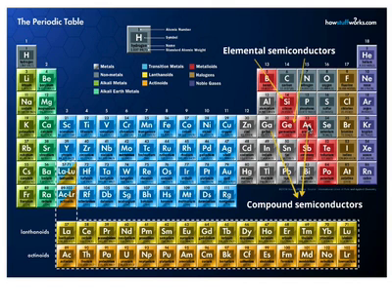It can be controlled by controlling the concentration of aluminum in gallium aluminum arsenide, for instance. So there's lots of very interesting engineering that happens. You can also, of course, combine more than 3. You can have 4. It's much more difficult to do, but it gives you more flexibility in your design of your materials.